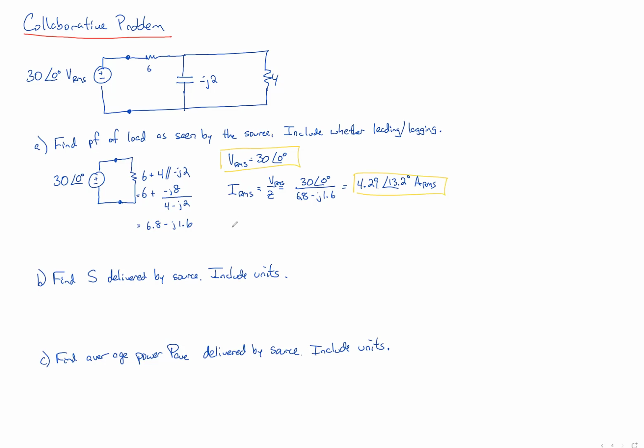What is the power factor? What's the formula for the power factor from our first page? It's the cosine of theta. Does it matter which comes first? No, it doesn't. So put either of them first. We always want to measure phases relative to voltage, so it kind of makes sense to put the voltage second.